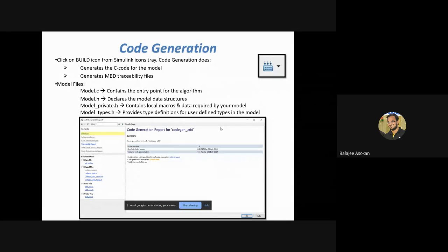In the code generation part, we have defined the data type, dimension, and all other things. Since all of these were defined, we will go ahead to do the code generation at this stage. Even in my SLDD file, that is the data dictionary, we have defined this part of it: whether it's my input signal, an output signal, or a calibration, what should be the corresponding header file name and all. All of this we will define, and based on that my code will be generated.